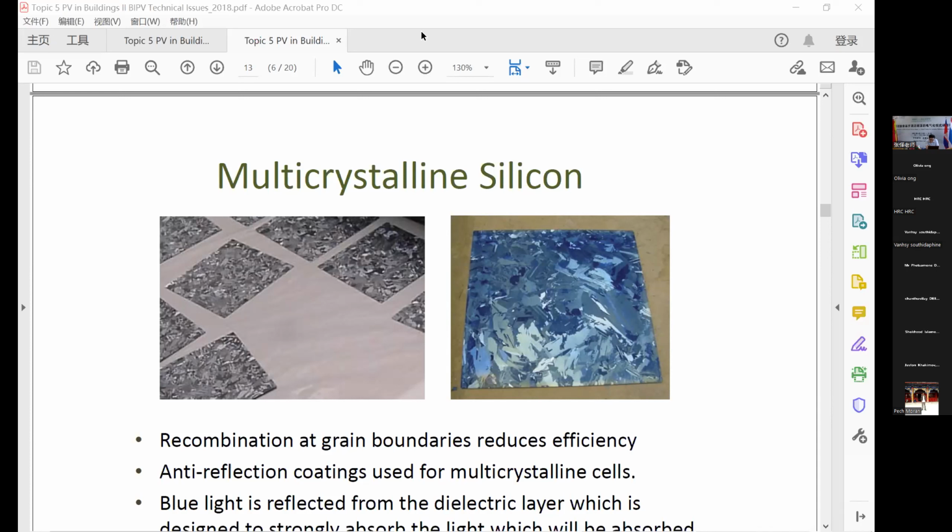Tandem solar cells are very expensive, even though their power conversion efficiency is higher than 50%, because they use different semiconductor materials. Normally, tandem solar cells have two problems: one is the expensive semiconductor materials, and the second is the junction compatibility between different semiconductors, which results in a huge series resistance loss.